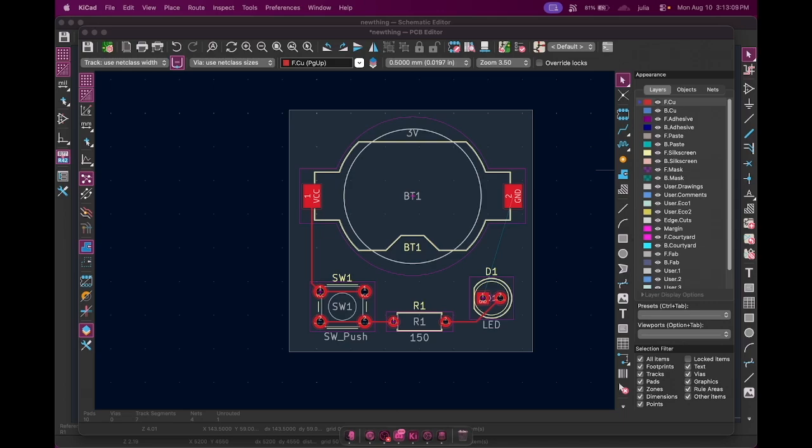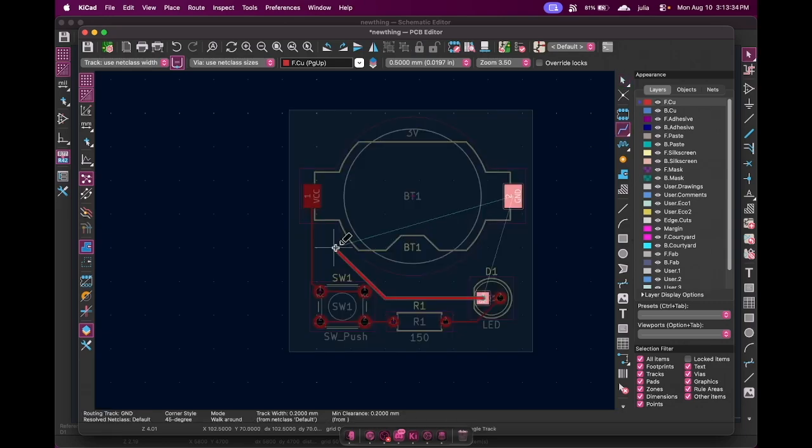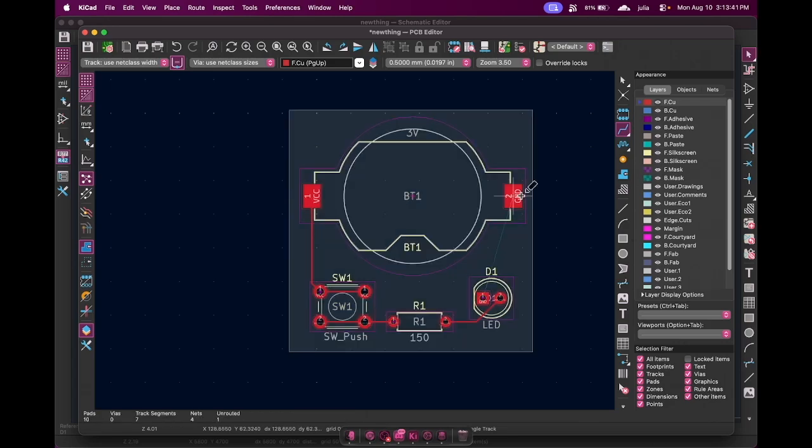Yeah. So the ground plane is basically the same thing as a net, except it's going to cover the entire board. When you have circuits that have more pins that need ground, this is going to be useful. If you had multiple pins all over the board and had to make traces everywhere, that would be painful, which is why the ground plane exists. So how are you going to make the ground plane?